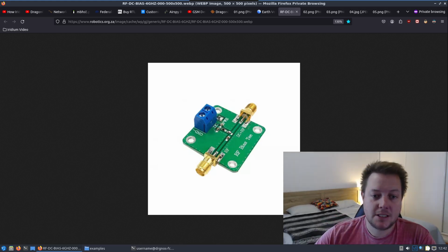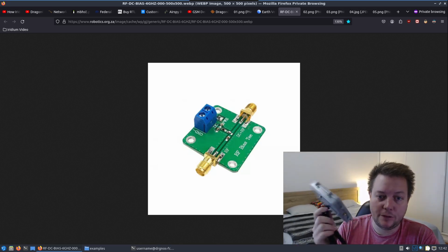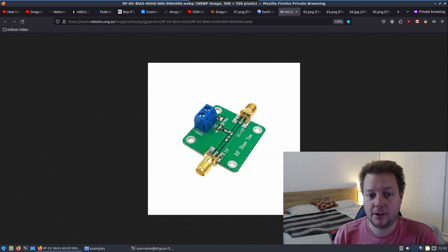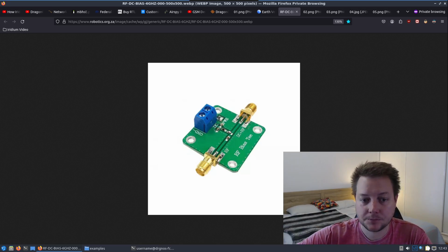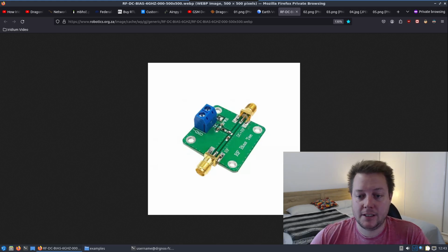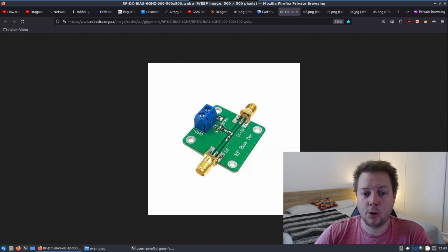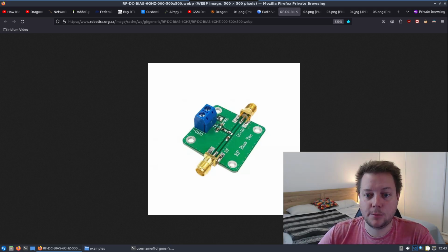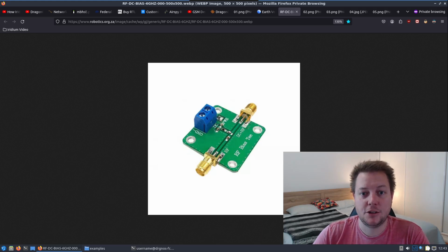If you are not using the same antenna that I am, you'll have to confirm whether or not your active type antenna is powered externally with its own power cable or requires power from the bias T of your SDR. If your antenna is a passive type antenna, you won't need any electricity to power it at all. Please double check and then triple check whether or not you need to change the following setting, because I won't be held responsible for any damage you do to your equipment because you sent a voltage somewhere it shouldn't have been.